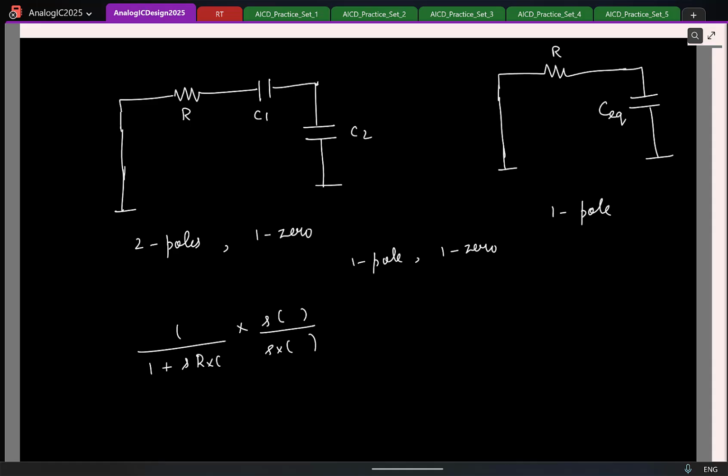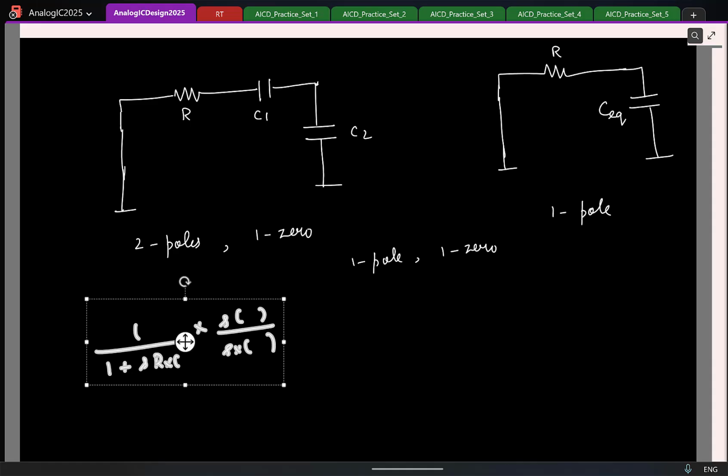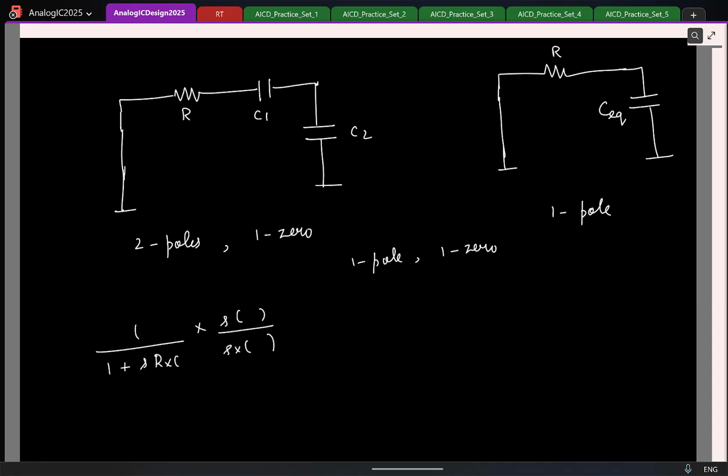So if you have taken control systems, what is this called? Okay, this is called the transfer function. Yes, if you have a pole zero cancellation happening, those state variables are called what states? If you have taken it, these are called uncontrollable or unobservable states. Have you heard this term before? So what that means is, in general, if you have an uncontrollable or unobservable state, you will end up with a pole zero cancellation.